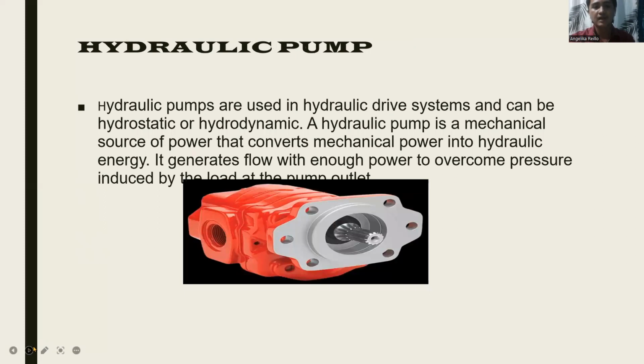Hydraulic pump. Hydraulic pumps are used in hydraulic drive systems and can be hydrostatic or hydrodynamic. A hydraulic pump is a mechanical source of power that converts mechanical power into hydraulic energy. It generates flow with enough power to overcome pressure introduced by the load at the pump outlet.